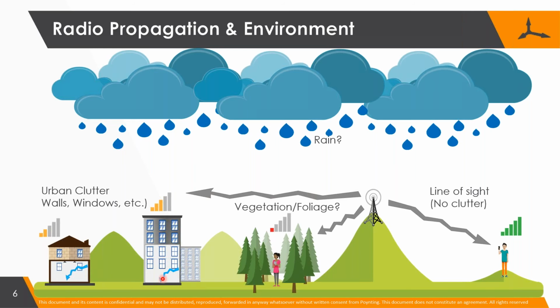We find that the drop you see over there is roughly about 16 dB in total. Not only is there a drop in signal in terms of penetrating, it's also a lot of multipath, because the higher frequencies will pass through the windows, doors, and so forth, but they will reflect and, in a sense, make the reliability of a connection with antennas indoors very bad. So getting outdoors, certainly in these cases, is a massive advantage.